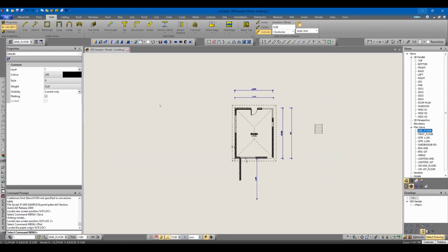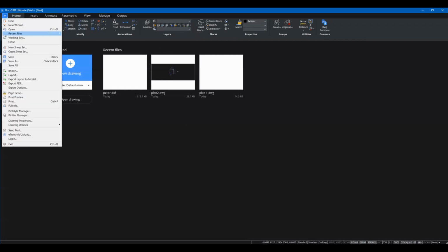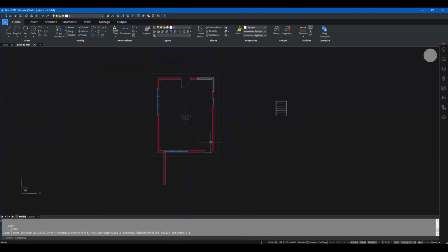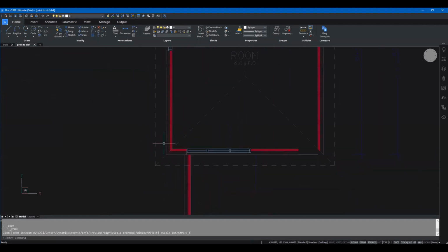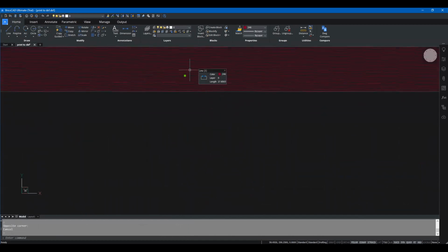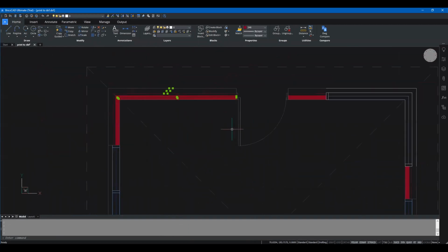This time it's super, super fast, no processing whatsoever. It's basically putting it straight out, all as line work, smashed to zillions of bits. If I go File, Open again, DXF, print to DXF, what I've got now is an exact copy. My line work across my hatching has been smashed to lines. My solid fill is hundreds and hundreds of lines.